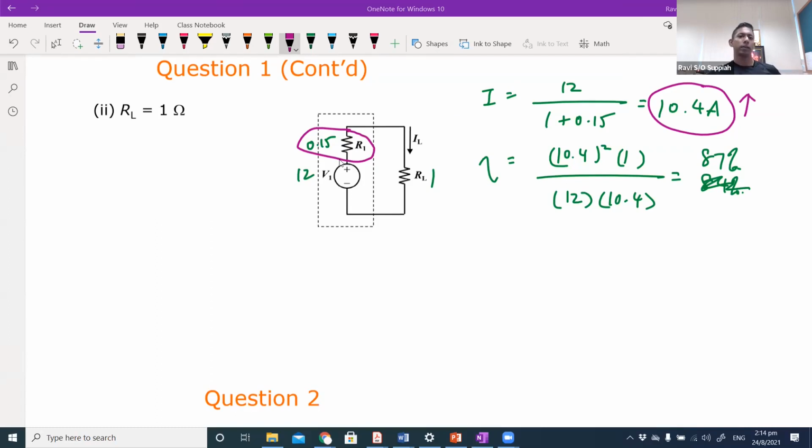Different cables have very different efficiencies. We have seen that a lot, where when we measure some cables from 5 volt, you get close to 5 volt. In some cases, the voltage can drop significantly to 4.5, 4.4, or so on. That means the voltage drop through the resistance of the cable itself is so much. So these are things that we generally overlook, but actually they can play a part.